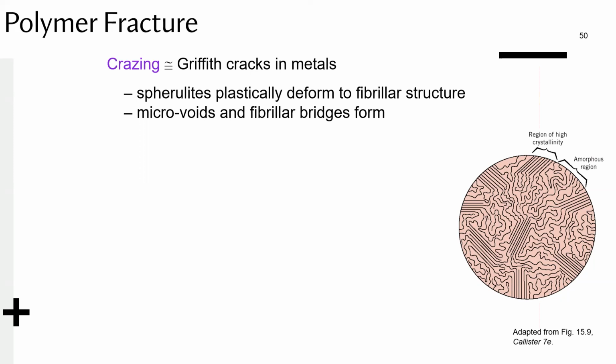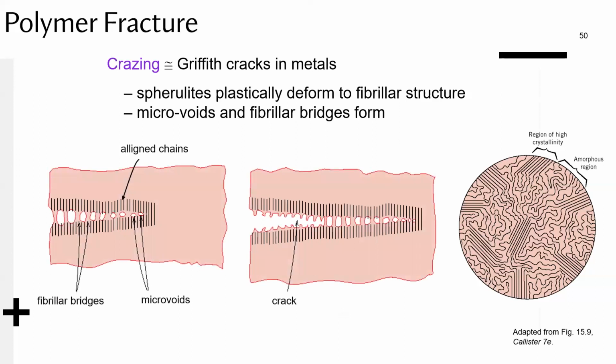Now, similarly, when it comes to failure, if we've already seen that highly cross-linked and crystalline materials behave differently from amorphous materials, you can imagine that this would cause a localized, distinct behavior in a semi-crystalline polymer. So this is exactly what this mode of failure is telling us. This is a schematic showing what happens, and that is you can see these microvoids, and these happen in the regions where they're more prone to failure.